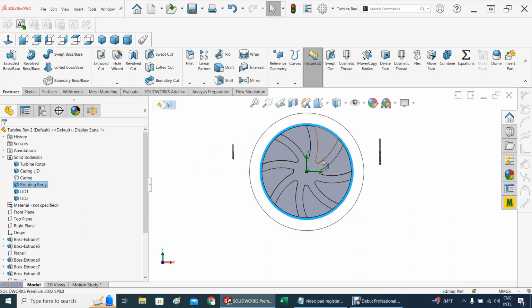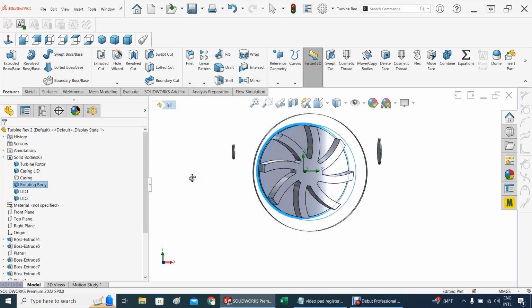For example, if this is going to be at 0 RPM at one point in time, that will provide the maximum torque, the kind of holding torque that is required for this not to move as water gets in at 40 psi and is rushed out this way. So that would be the maximum holding torque for calculation, but as soon as it starts to spin, the extraction of torque gets diminished.